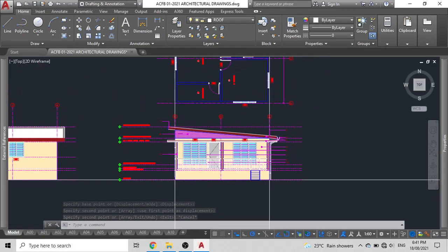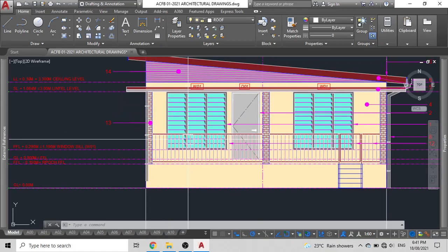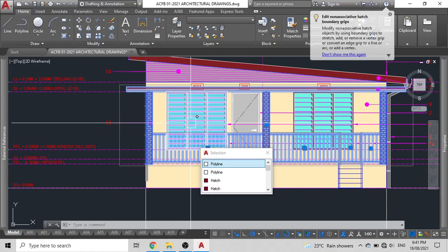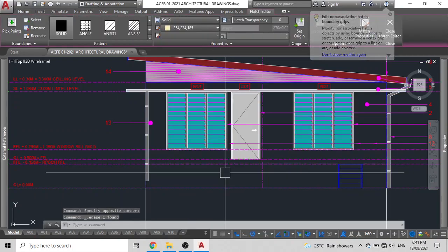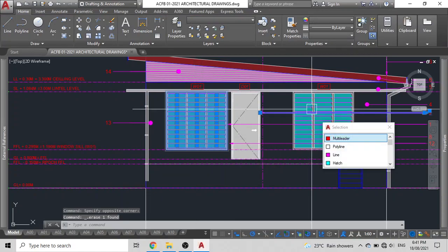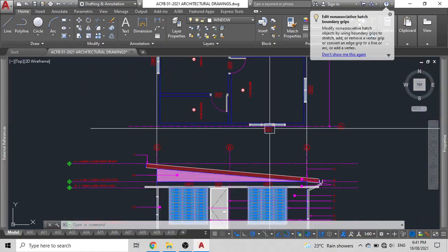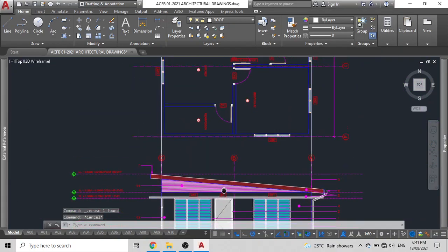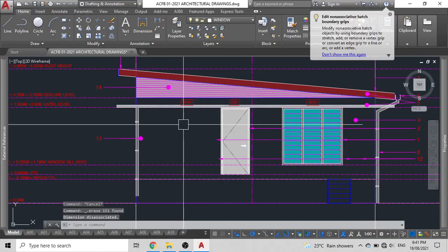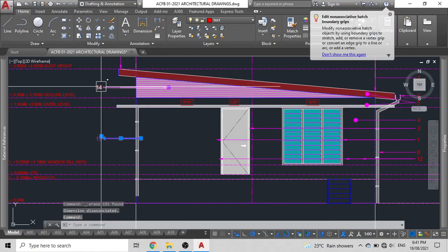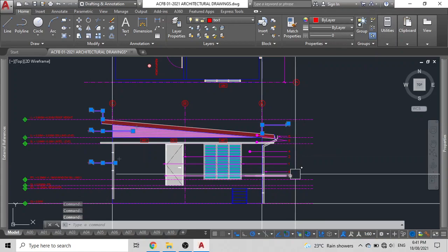So remove anything that is unnecessary from here. Do not orient the drawing yet. Just remove what things are unnecessary, such as this porch. Then delete this. Delete all the unnecessary windows. In this elevation, we are using window number 1, so you can leave one of the window, and we are also having a door one, so you can leave one of the door ones, but otherwise delete all. Remove the keys if they are unnecessary, because what you'll have to do, just simply copy from the other side and bring it this side.